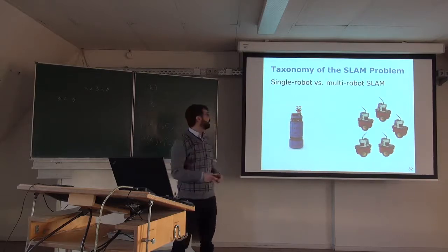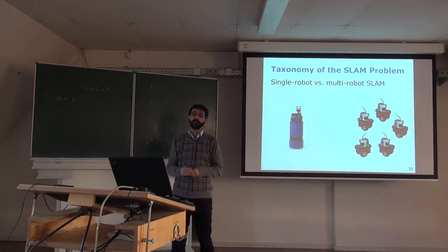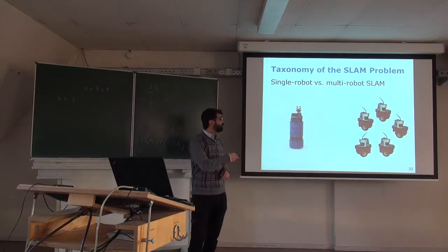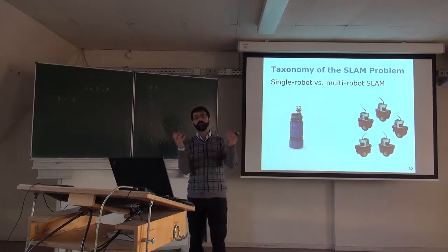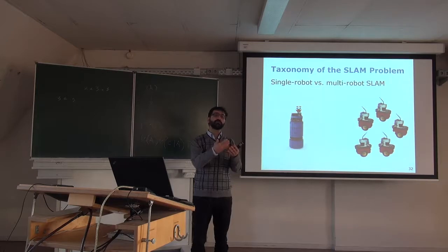But if you want to do something meaningful in a distributed fashion, then things are a bit more complicated. You need to find a way of communicating part of the maps between different robots. You need to find a way for each individual robot to recognize where another robot is, or to plan, if you are on the active part, a rendezvous point: the robots think they should be close by, and they just say, oh, let's meet, so we are sure that we are close by, and so on.